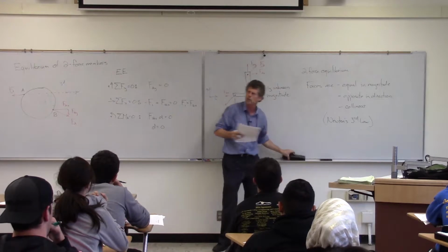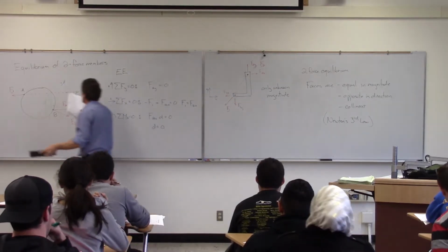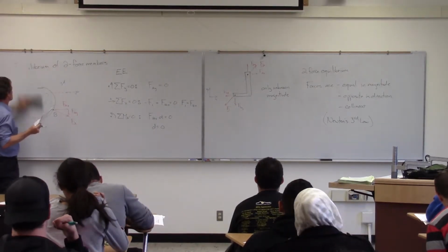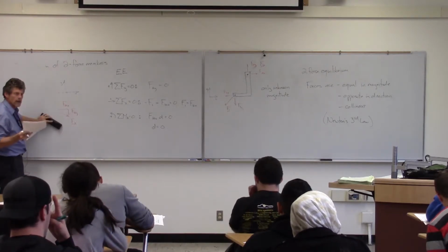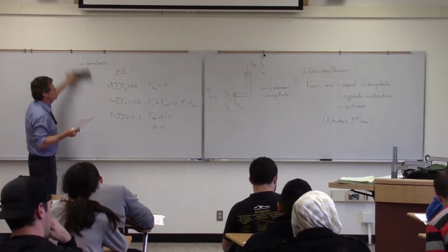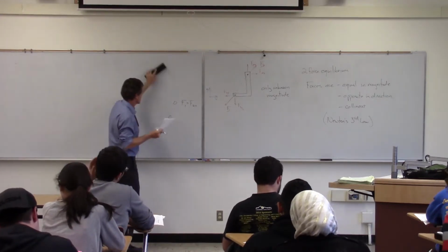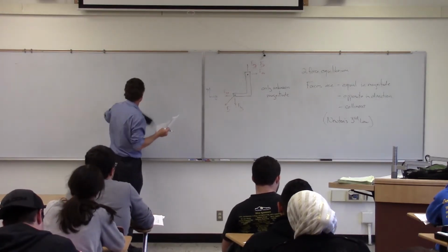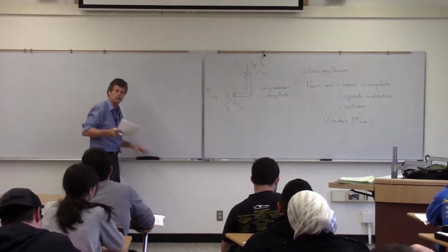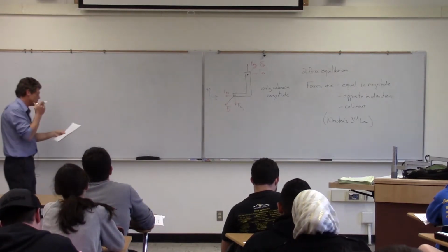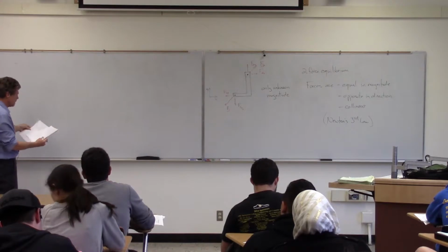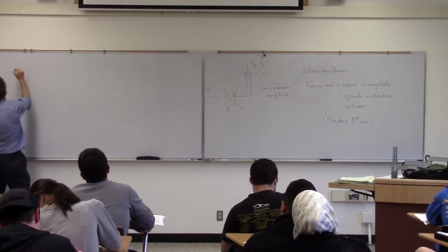Actually, we'll go through a curved example today. If we can recognize the fact that it's two forces, then we've eliminated that direction. We've got the direction figured out already. Now, all bets are off when we go to three pins. So three-force members don't necessarily work, but we will talk about that.